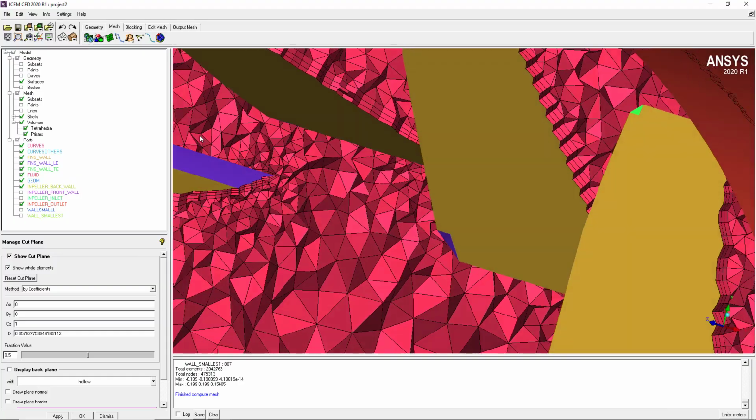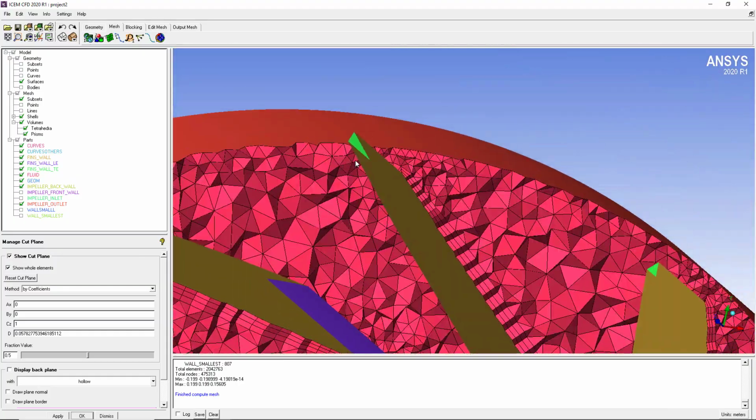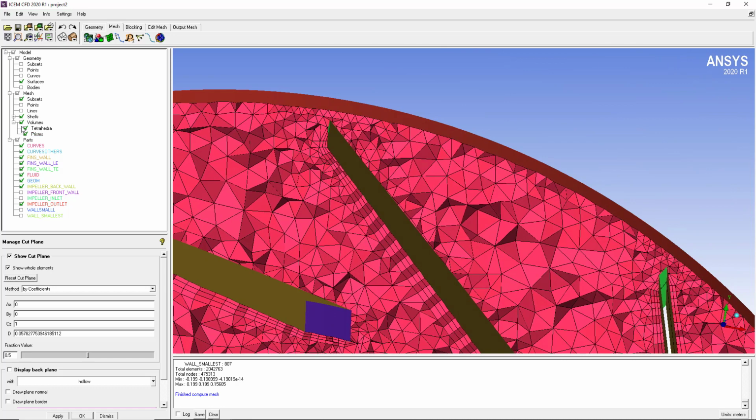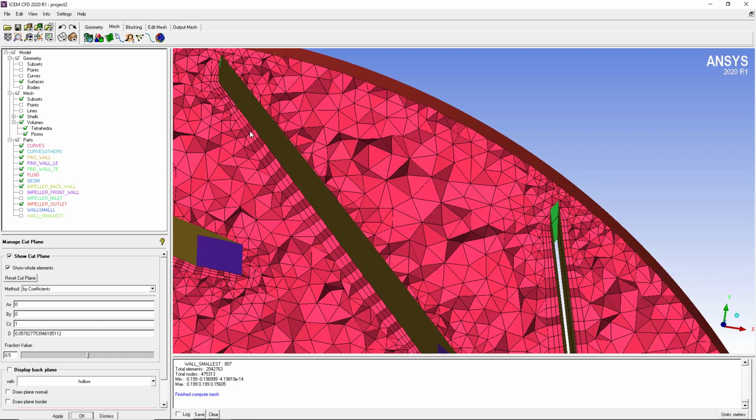After creating the prism mesh, we can see that we have these prisms, and the only volume elements we have here are tetrahedron and prism, and there are no pyramid elements here. This is the effect of turning off the stair step option. The second thing is that we have reduced the quality for the prism mesh, so it didn't try to create the pyramids.